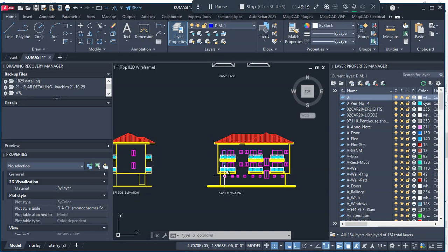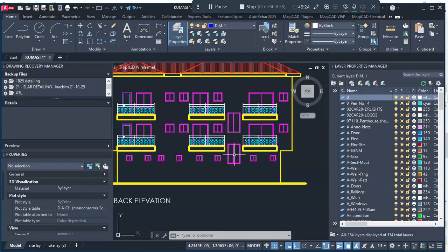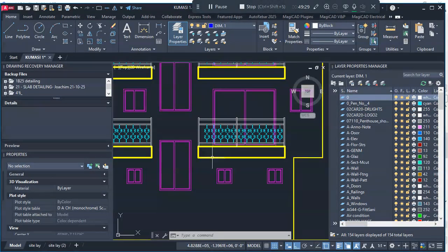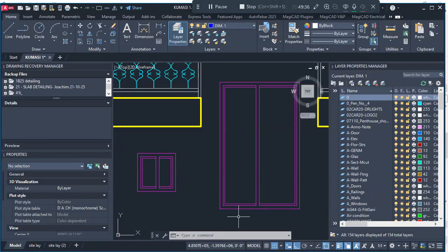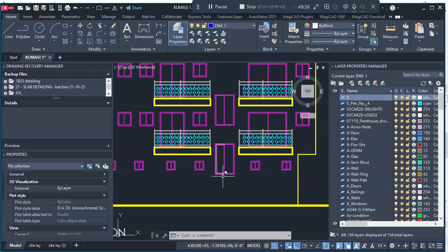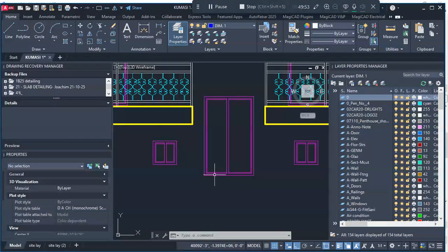There's this big window here. It's looking like it moves to the upper floor, that's the first floor. You get it, but it doesn't flush with this here. So I'm going to assume that usually the sill height for a window is, some use 900, some use 1000, and I'm going to assume the same for this side.